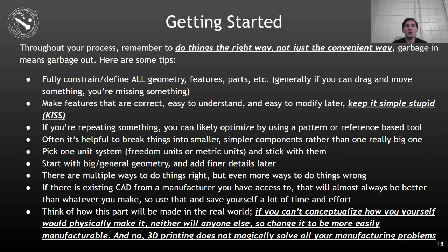And so, another thing with making assemblies for things, it can often be better to have multiple smaller and simpler parts rather than trying to combine a bunch of things all into one big file. For example, at my undergrad, there was one group that wanted to make a custom drone, all 3D printed and everything. The very first print that they did, I walked in on it after it was 37 hours in. They decided to print the entire thing all at once. And the only way that they could fit it was to fit it in diagonally all weird, with a whole bunch of support material underneath it, one single solid part.